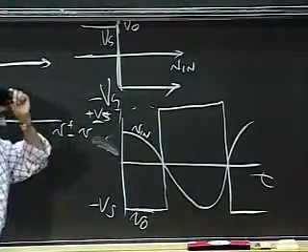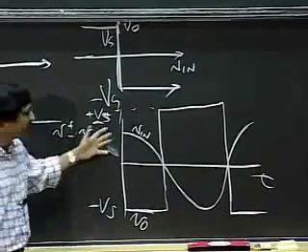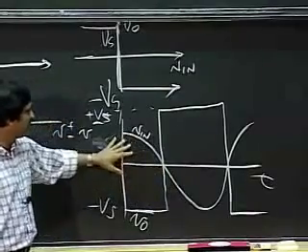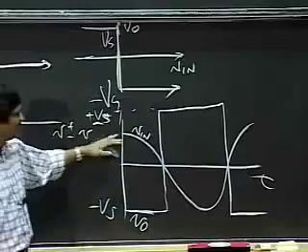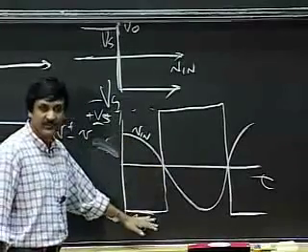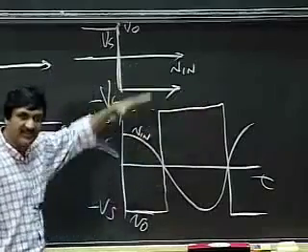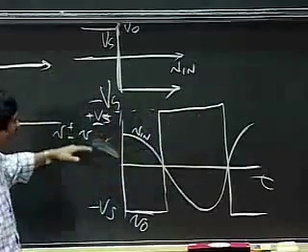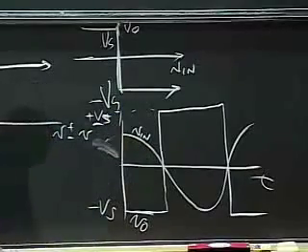Let's say, for example, I want to build a little digital circuit that is fed ones and zeros. So I can use a comparator to turn my V in voltage into a sequence of ones and zeros. Okay, so when V in is positive, I produce a 0. When V in is negative, I produce a 1. So I can get this 1, 0, 1, 0 sequence coming out corresponding to the values of V in being greater or less than 0.